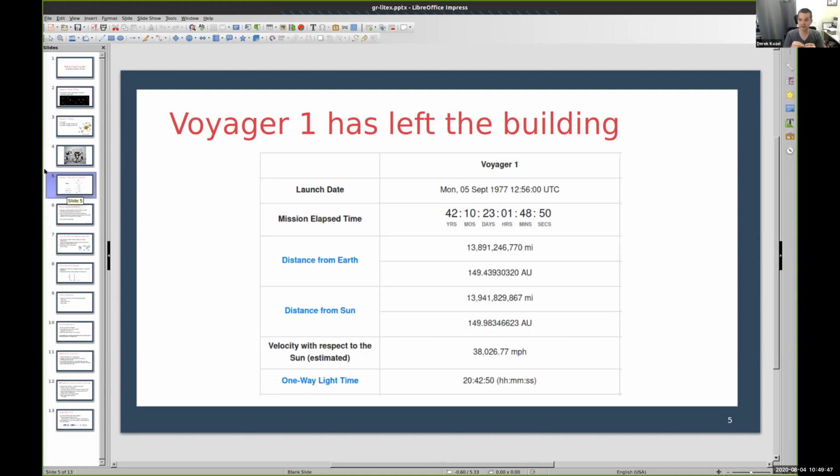The data file that everyone has downloaded is also actually the raw voltage data. And what you'd be looking for, if you did go in and try and very precisely look at the signal, is a continuous sine wave, and every now and then its phase would instantaneously flip 180 degrees. And that's what signals a 0 or a 1. So this is called binary phase shift keying. It's using a 39-year-old variant of it, so it's not quite exactly what we canonically call BPSK now, but it's 99% the same idea.